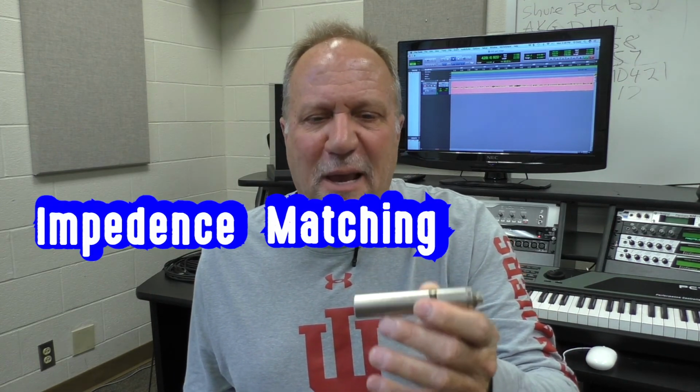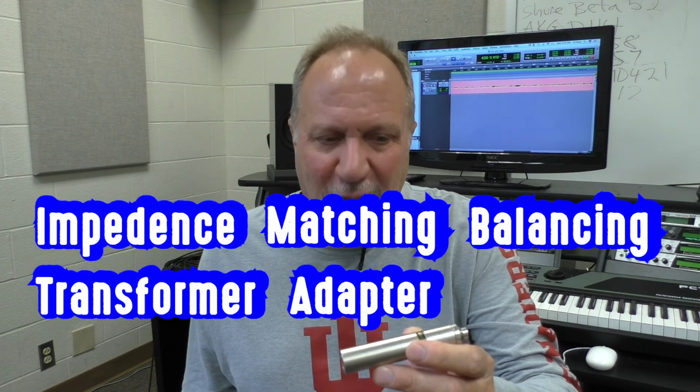Right here we have a handy dandy little device. It's an impedance matching balancing transformer adapter. If you look here at the one end, it has a 1/4 inch input, so you can plug your guitar, your bass, or your instrument right in there. And the other end has an XLR output on it, like a microphone, so you can plug it into a mic input. So this brings the signal down to microphone level, it balances it, and it converts its impedance to the signal to be low enough to be able to plug into the microphone input without causing problems.